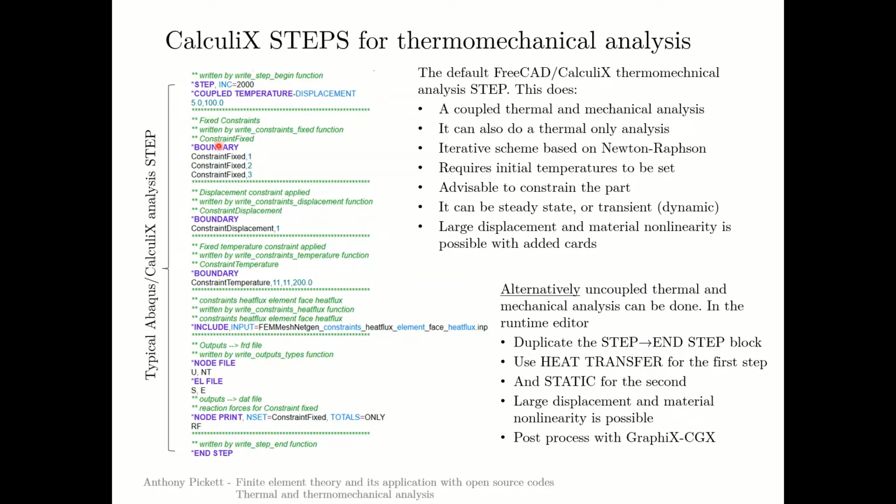A step is basically one analysis. So you have a starting step, if you like, and an end step. You could have another analysis after this, in which case you would have a step, a load of information, and then an end step. And information from this analysis would be fed through into the second analysis, and so on.